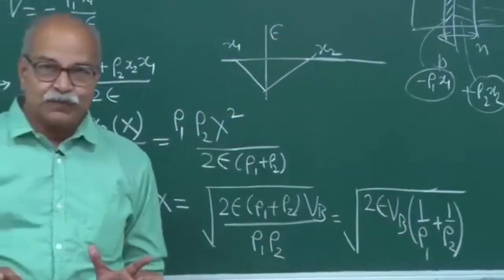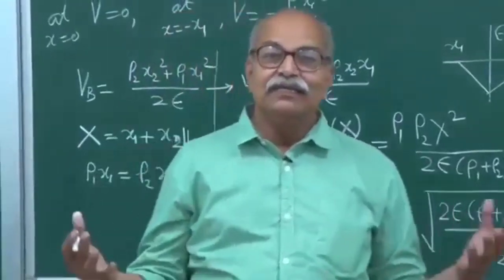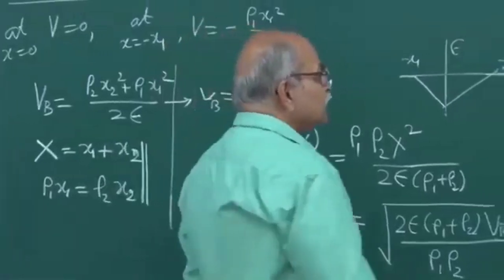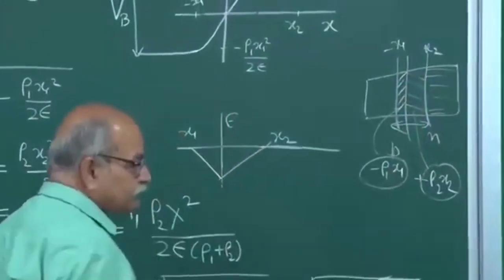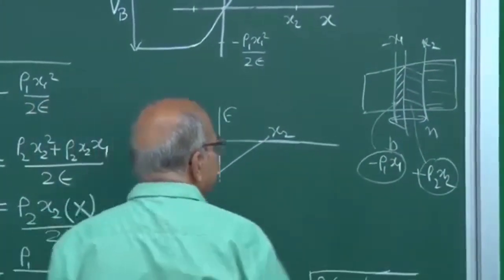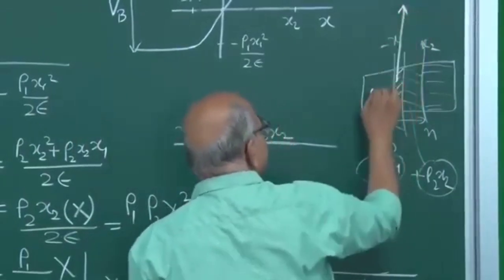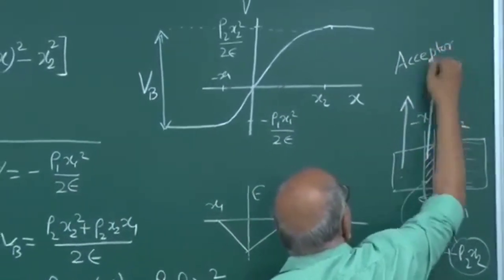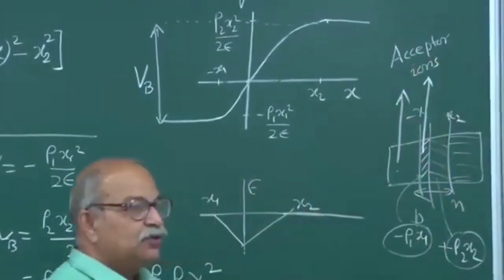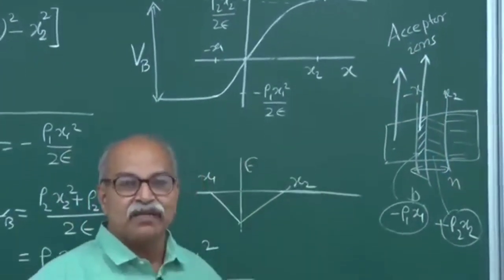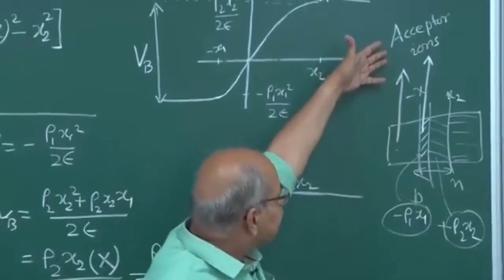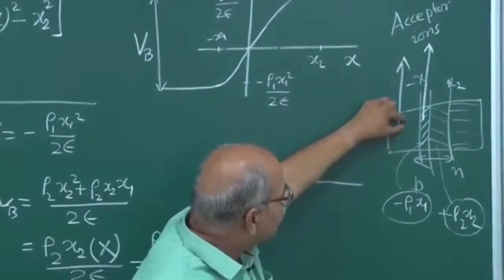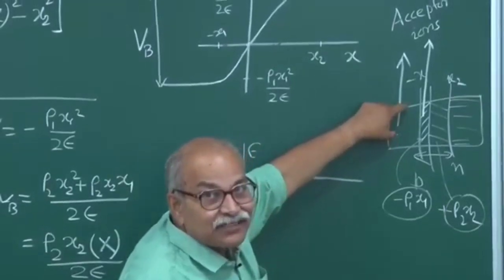These rho 1 and rho 2 are related to the concentration of impurities that we have doped, right? Because how are you getting charges in the depletion layer? In the depletion layer you are getting charges because you have put impurities. This is p side, so you have put acceptor impurities. Acceptor ions are there, right? When you diffuse boron, for example, or any trivalent atom in silicon, then you have created a hole there and then the ion which is there, and this whole thing is neutral.